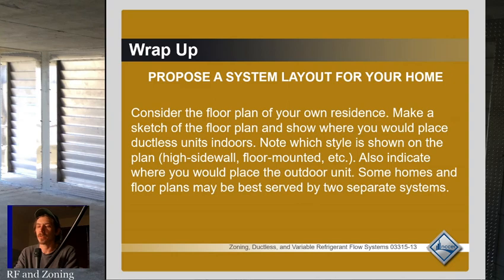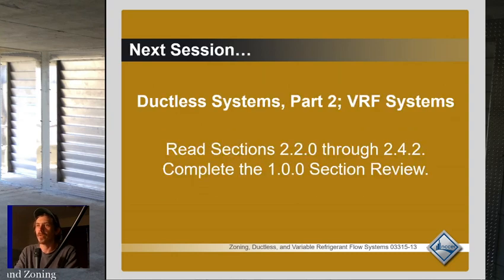But like I said, what you're going to see soon is a lot of mini splits that have more controls on them to control that humidity problem, but the humidity problem has been a relatively common occurrence with small houses and things like that that have been designed with all mini splits, because they tend to be grossly oversized.